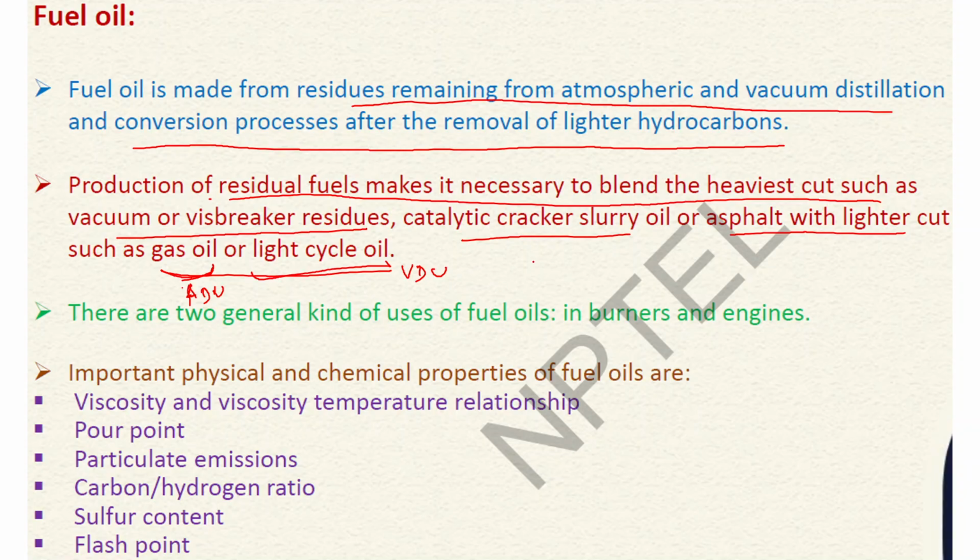These lighter cuts are collectively called cutter stock. This residual oil plus cutter stock is mostly taken in a 70 to 30 ratio. This is called fuel oil.